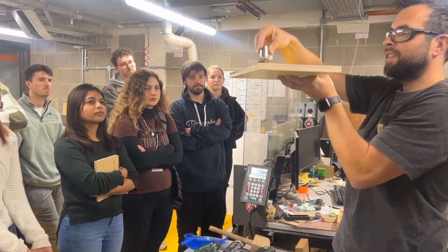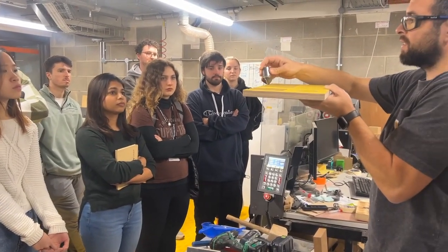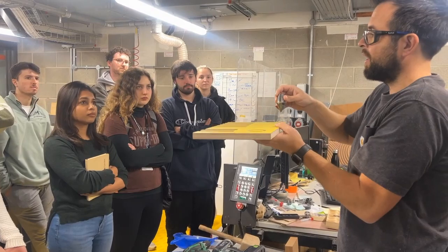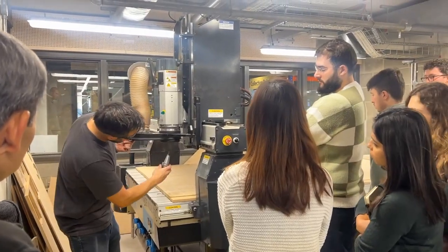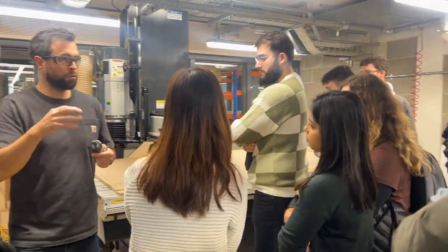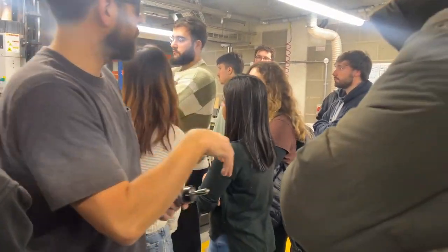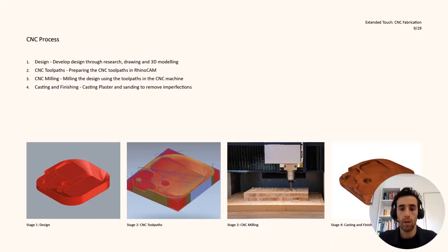So they're V-tip cutters, and they can be used to put chamfers on edges. They can be used to pick up lines for engraving, and you can get much smaller versions of this. It will actually pick up the tool in a tool cone using air suction, and that's a way of using multiple tools on a program without me having to change them over and over again.